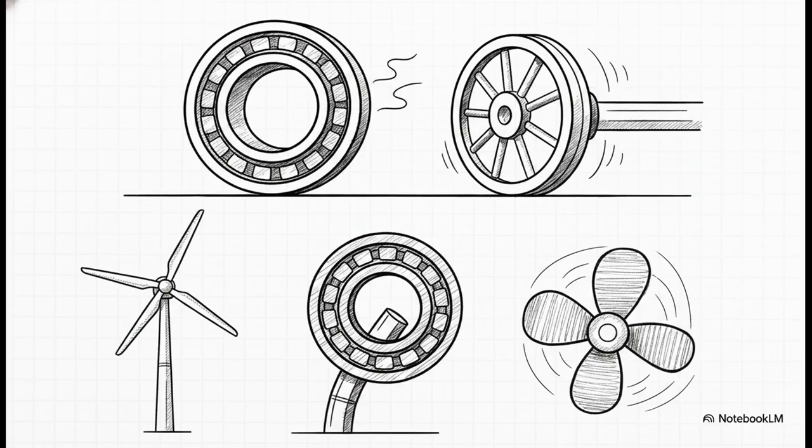Then you've got spherical roller bearings. These things survive conditions that would rapidly destroy more delicate designs. They handle enormous radial loads while taking up to 2.5 degrees of misalignment, making them the absolute go-to for massive applications, like wind turbine main shafts and ship propellers.